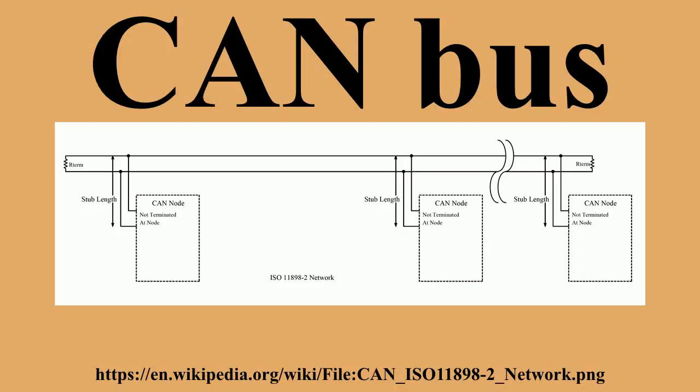Transfer layer. Most of the CAN standard applies to the transfer layer. The transfer layer receives messages from the physical layer and transmits those messages to the object layer. The transfer layer is responsible for bit timing and synchronization, message framing, arbitration, acknowledgement, error detection and signaling, and fault confinement. It performs fault confinement, error detection, message validation, acknowledgement, arbitration, message framing, transfer rate and timing, information routing.